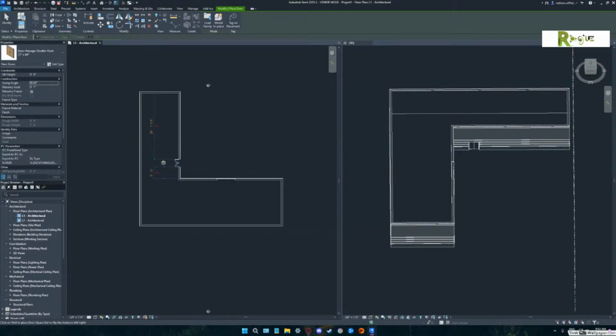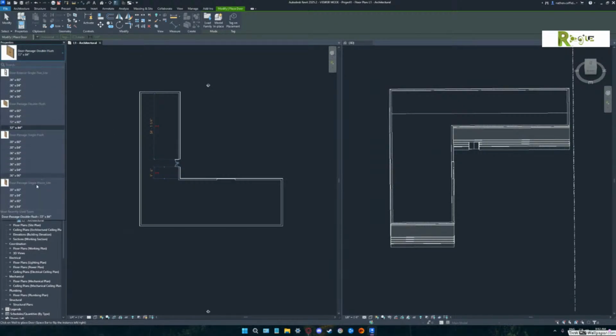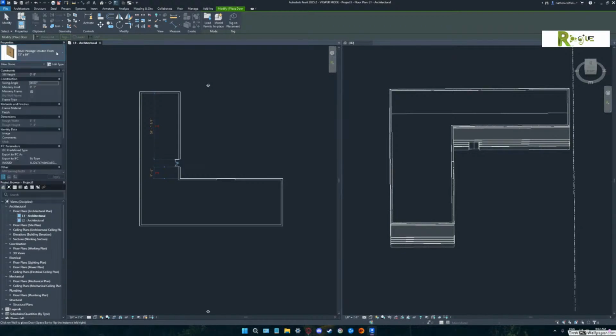How about a garage door? Can you put a garage door into one end? And you see, that was why I was asking you to do that. I don't know their template anymore, but I had a feeling there wasn't going to be a garage door in here. So that's where people get very frustrated in Revit, because that means that you have to load a family. Now, for the typical ones, they've given us some, and we're going to see how good your load did.